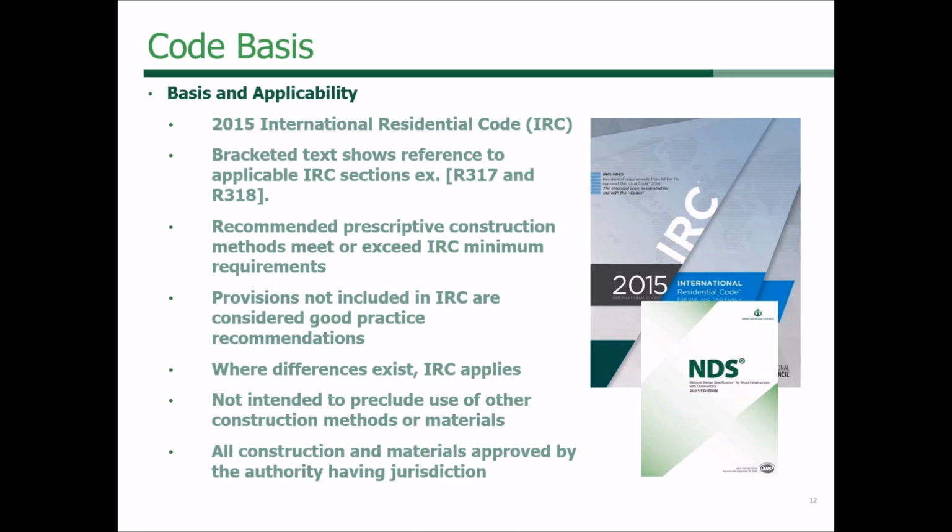However, there are instances when DCA6 goes beyond the IRC, and there's also good information in DCA6 if you are designing a commercial deck or something like that, that I at least would have found helpful when I was designing, to say, oh, okay, this is kind of the assumptions they made, I should do the same thing for mine. So DCA6 does not cover commercial or high-rise residential even, but it does have some information in it that will be useful for you.